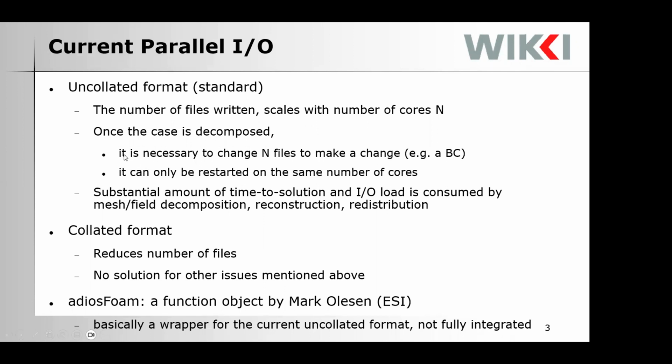Once the case is decomposed, you have another problem: if you want to change some boundary, for example, from fixed value to zero gradient, you have to do it 8 times if you have 8 processor directories. You can also only restart from the same number of cores, right? And a substantial amount of time to solution goes into decomposition, reconstruction, or redistribution of your case.